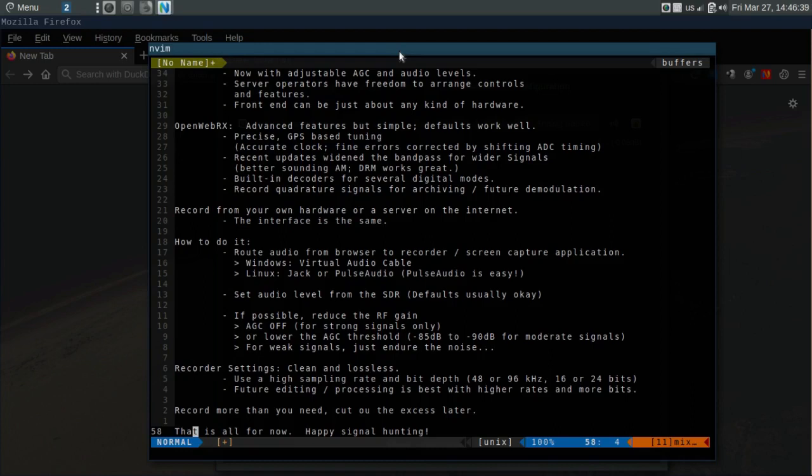Podcasters will normalize their audio so that their peaks are about 1 dB below zero. You don't have to be quite so precise with it. If you're more than a couple of dB below the top level in the digital domain, that's okay. The default audio levels from WebSDR and OpenWebRX are pretty reasonable. You can more precisely set it if you want.